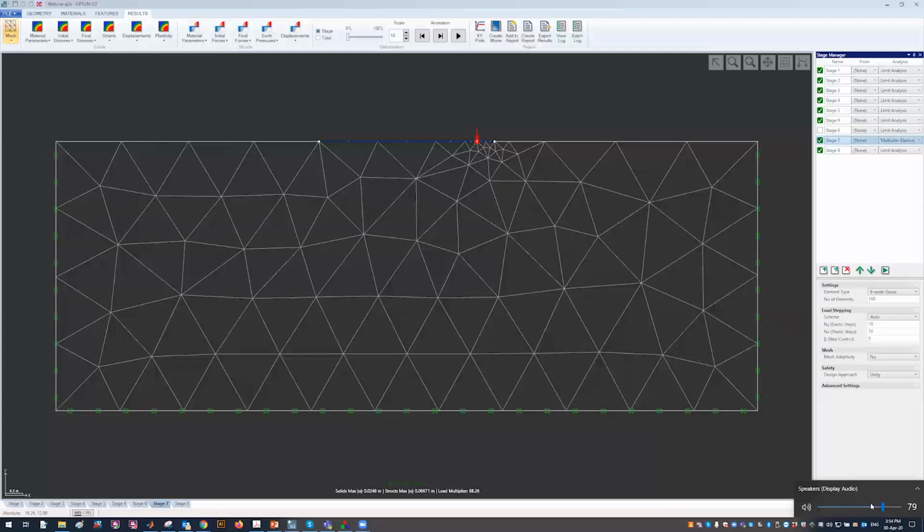I really enjoyed the way that you're dealing with the inclination of the loads, but my question is, sometimes we have a problem with a purely horizontal load at a certain depth without any vertical load apart from the surcharge load. Then we need to limit the deformations to elastic so that we don't let any plastic deformation take place within the soil. Would you recommend this methodology over Ka/Kp analysis, which is typically done for pure horizontal loads? This is my first question.